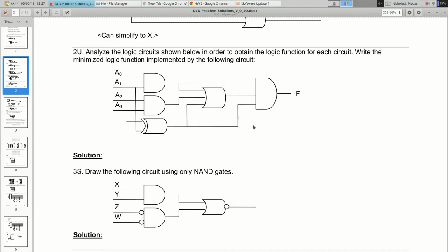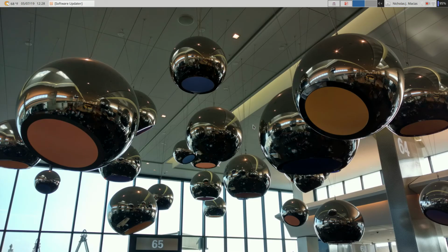All right, we've also got inputs A1 and A3 going into an XOR gate. So I'm going to call that part of my circuit F2. And to find F2, I'm just going to look at A1 and A3. And I'm going to do an exclusive OR on them. So if exactly one of those 2 is a 1, my XOR is going to be a 1.